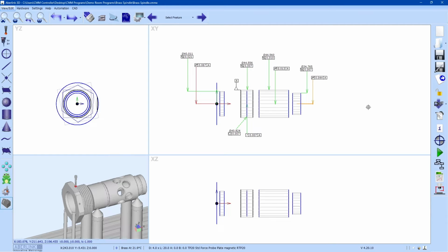This is really important for spindles and shafts, because if the diameter itself isn't round, say the diameter itself was like a hexagon, concentricity would still pass, but runout would fail, even if the axes were perfectly aligned. And obviously a drive shaft or a spindle not being round causes a lot of vibration, ultimately causing the thing to fail. So that's one really critical reason why I prefer runout over concentricity.